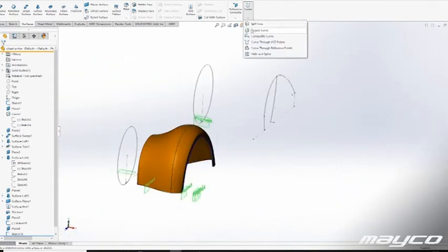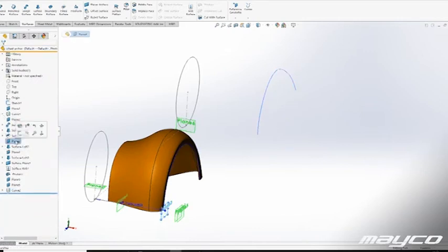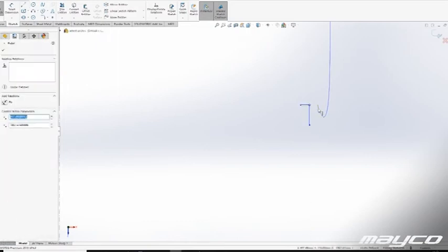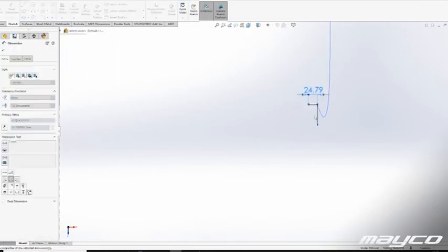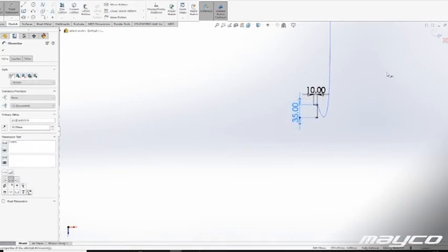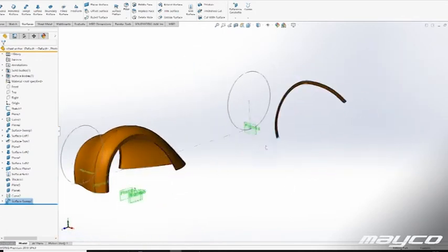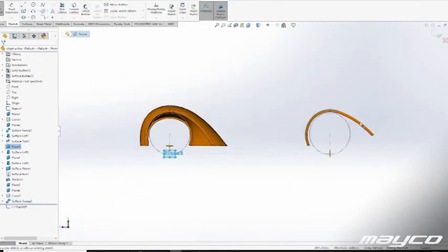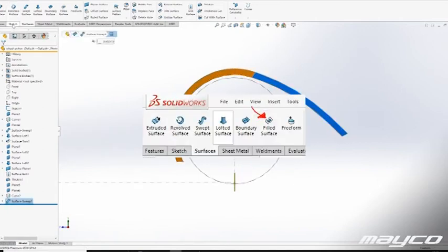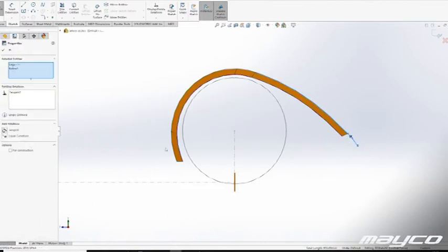Option 2 is that you use the fill feature. And what that does is that when you have a triangle shaped surface hole within several surfaces that come together and leave that triangle shape left open, you select all the edges surrounding that triangle, and then you say fill surface, and generally it will do that.